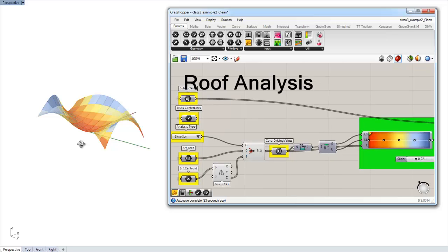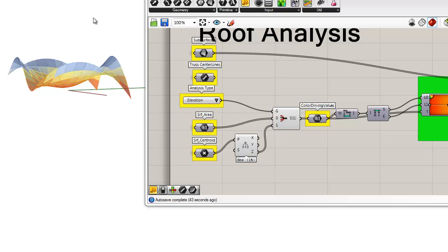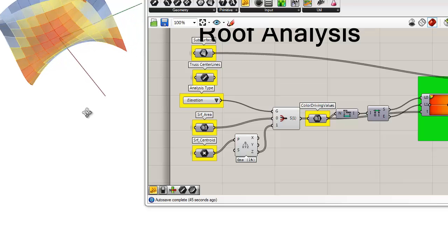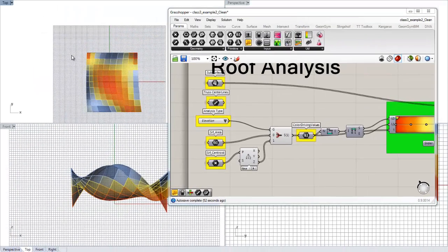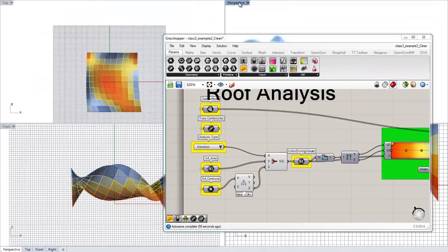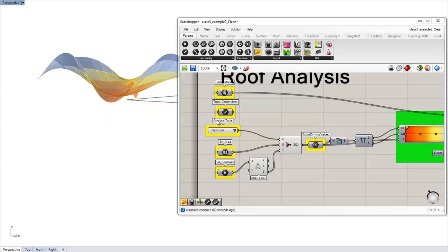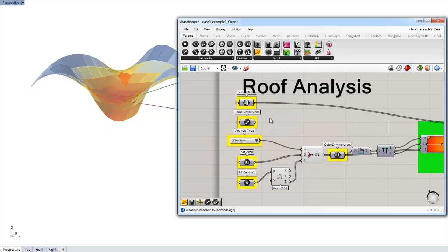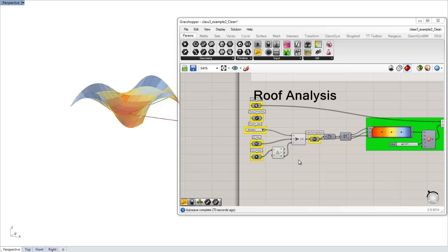Okay, so the next point is I want to set up in Rhino an attractor point, and I want to measure the distance between the attractor and the centroid and color code the surfaces based on that. So in Rhino, I don't know why my escape button doesn't work anymore. So since I can't go back to Rhino for some reason, I'm stuck. It's because I'm recording the screen and it doesn't work together. So I will just set up a point with 2 sliders on the XY plane, or whatever. I'm going to draw a circle in Grasshopper and just make a point go around the circle. So I just want to create some sort of attractor point.